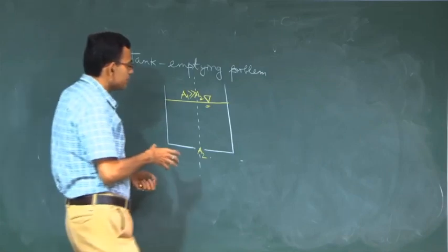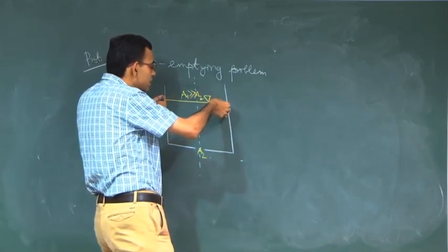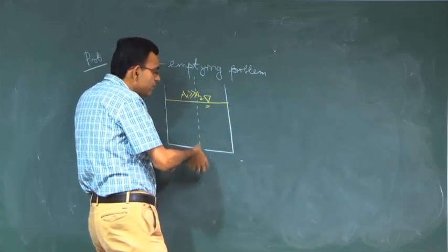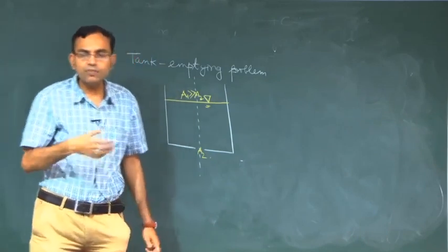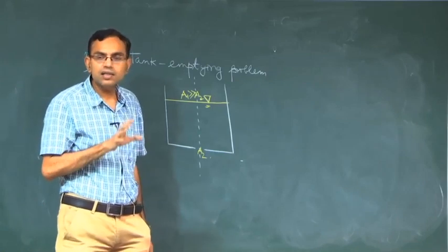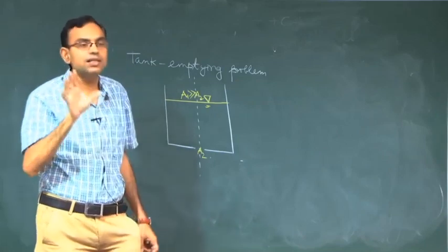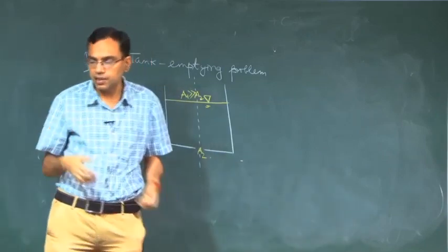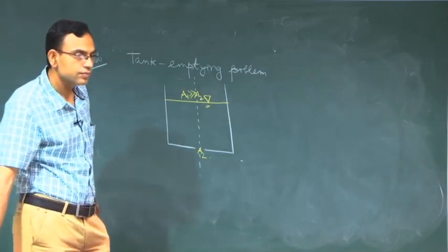Clearly, because the front is coming down as the fluid is getting out of this tank, the flow is unsteady, and even if all other assumptions of Bernoulli's equation are satisfied, the unsteady assumption may be questioned. So, it is better to keep the unsteady term and see in what situations it may or may not be neglected.